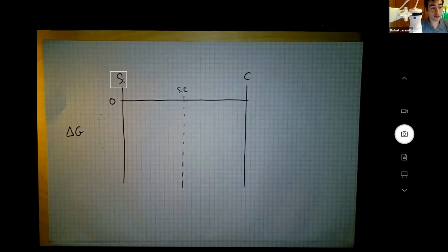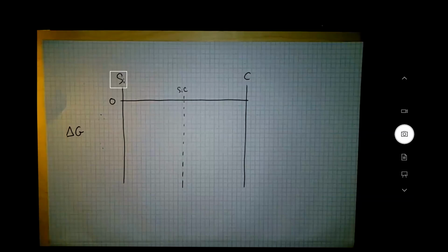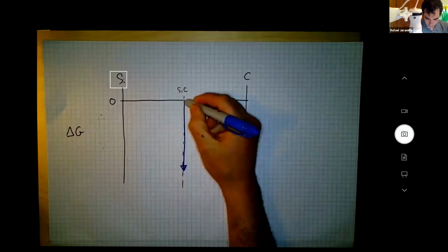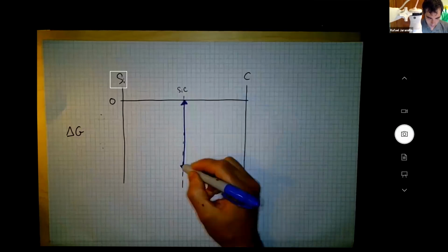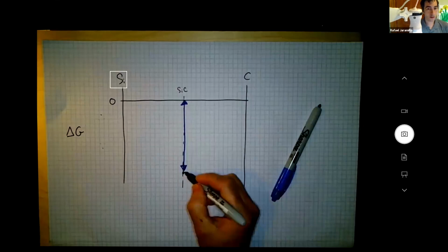So first off, do I need any solution models? Right, I don't need solution models because nature has informed solutions. So no need to model solutions. So what do I need instead of solution models? Just like the taut rope, like the lines. Yeah, all I need is a number to represent the free energy change on forming silicon carbide.